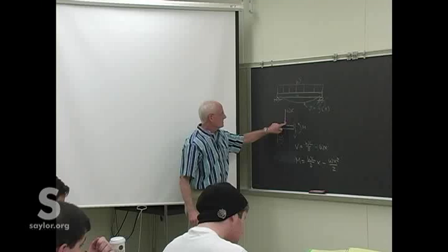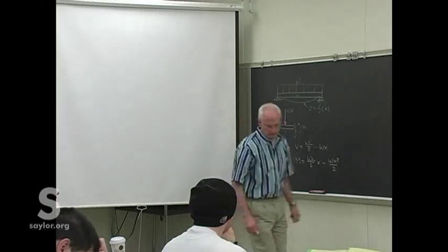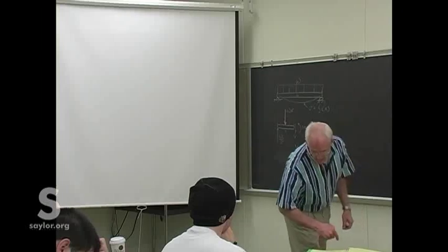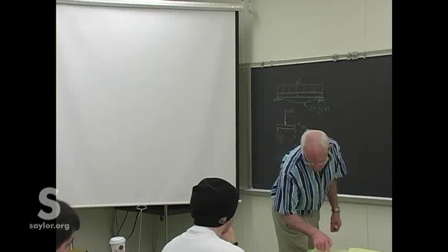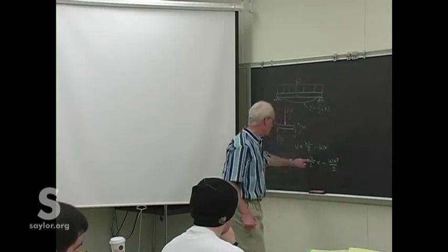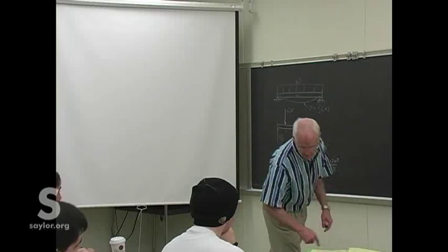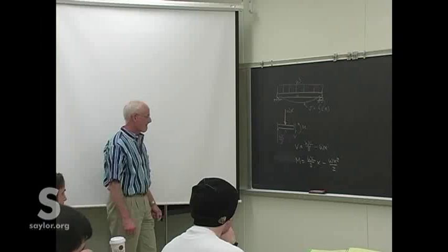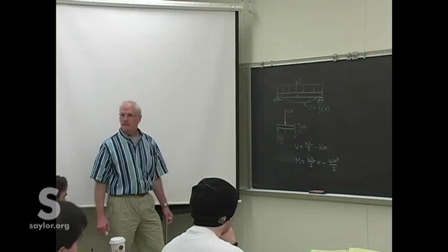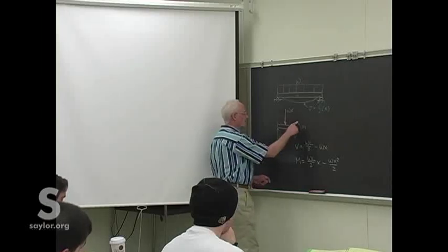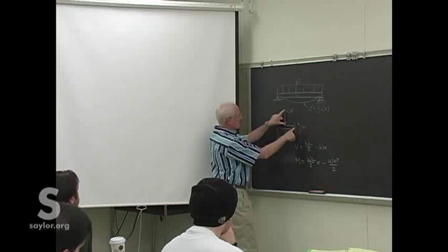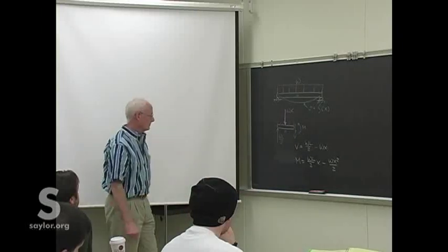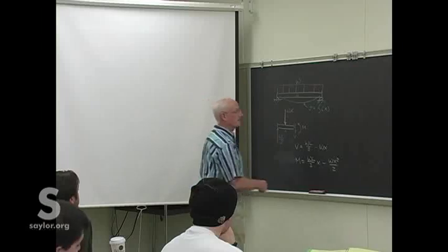That's the moment due to this taken about that point. So I think that should be okay. Yeah, that's okay. That all right, everybody? Okay with that one? This moment must equal the moment caused by the reaction plus the moment caused by the load, and there's no moment caused by the shear because that's right through that point.